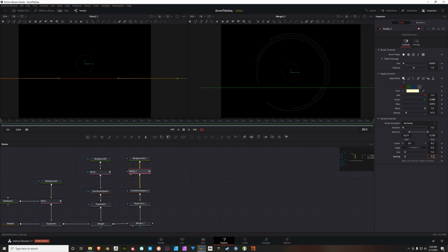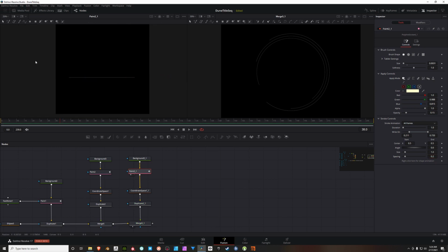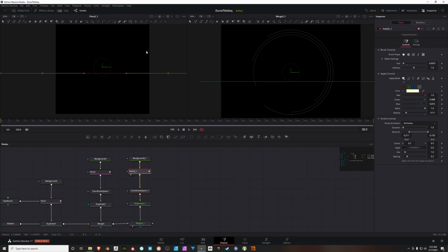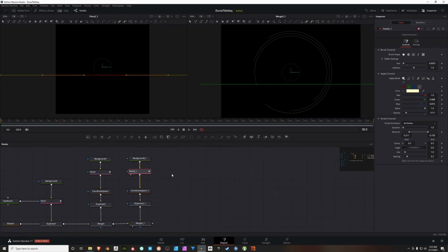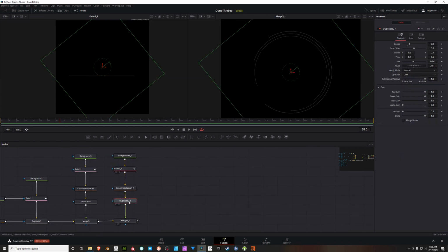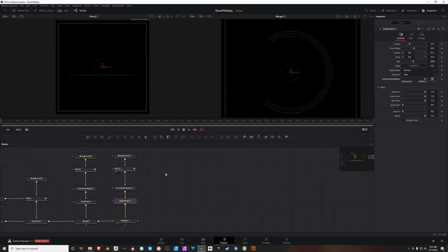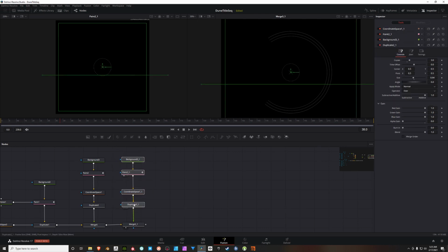I'm going to need to make this circle bigger, so just like I showed you before, I'll make sure all the points are selected. And using Shift and the arrow key, let's move it up on the y-axis here. And then I'm going to go down to the duplicate node. I'm going to change the angle of that back to 0. I'm going to add one more node to this, and that's going to be a transform node.